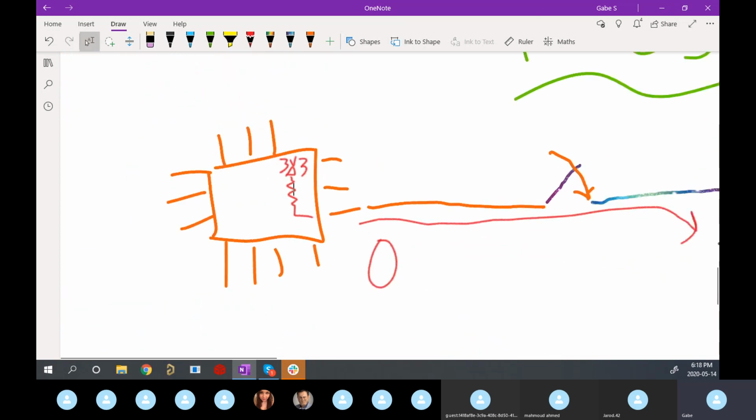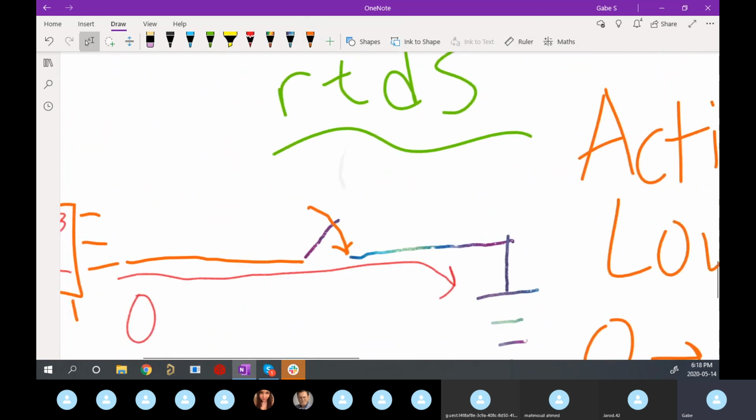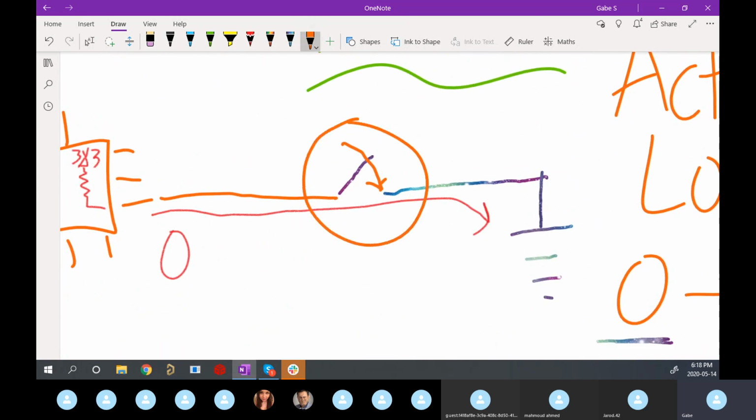What that does for us is that whenever this switch is not switched and not closed, this pin is actually floating without the resistor. Can you see that here? If this is open, then this pin is not connected to anything anymore. It's just this wire that's floating in space. It's not connected to ground, it's not connected to VCC anywhere. It's only through this internal pull-up that the pin has any connection.